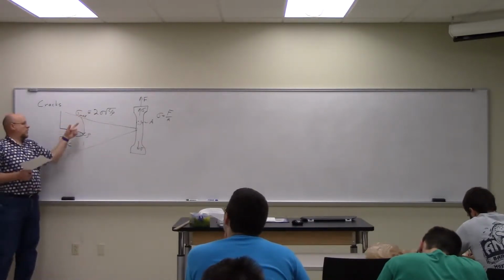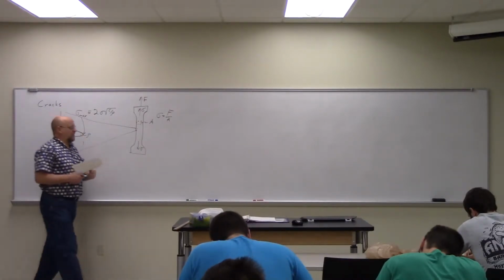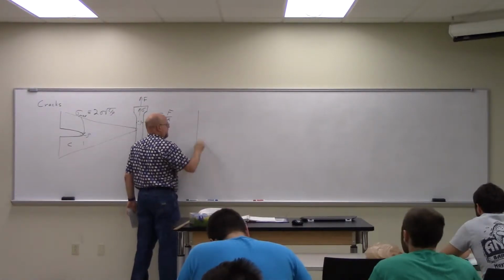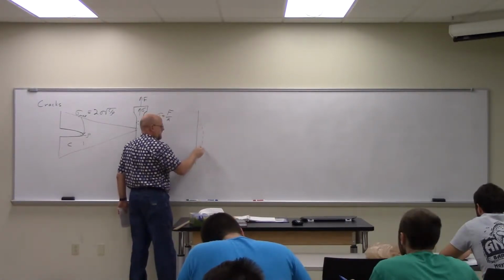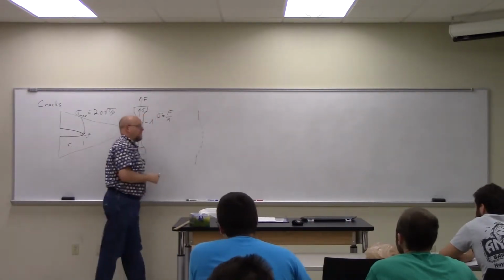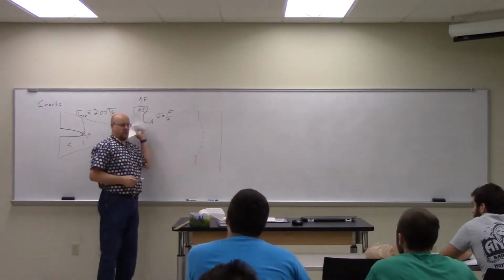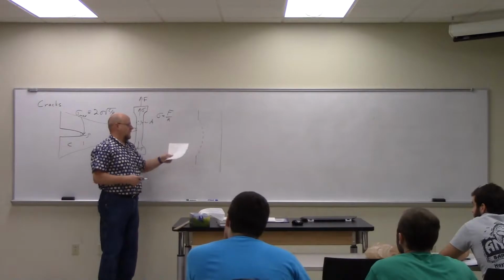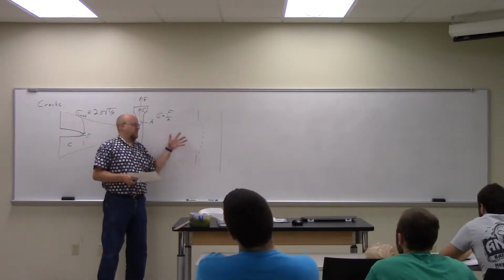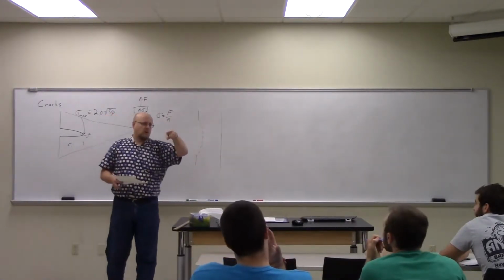And the approximation applies because it's a tight crack. If I took a big chunk of sample and instead cut out a piece like this out of my otherwise straight piece, I wouldn't use this approach, because here rho is bigger than C. I can do that macroscopically. I don't have to do cracking. There's no real stress concentration.